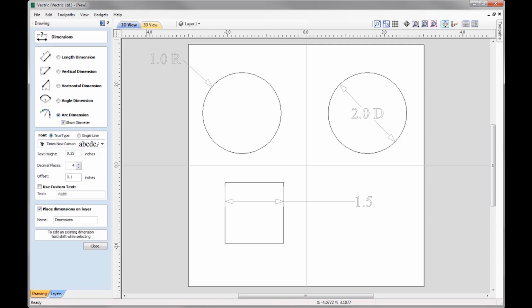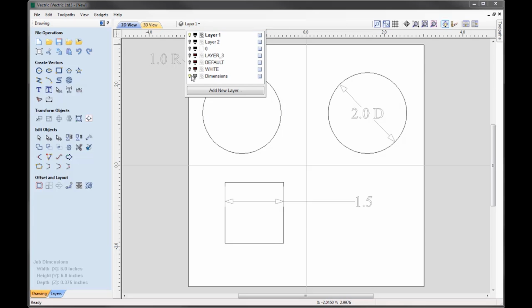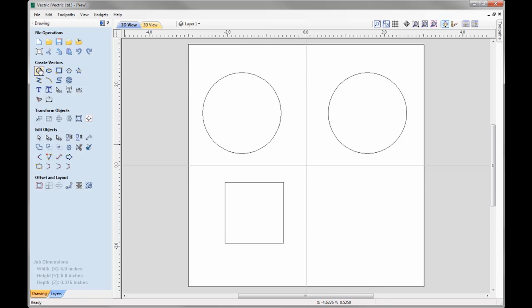Another enhancement we've made, which you saw briefly here, is the ability to edit shapes whilst in the relevant shapes form. So you saw that I held down Shift while selecting a dimension in order for us to edit that. Let's have a look at some of the other shapes that enable us to edit existing shapes. So we'll close that down. I'm going to go to the Layers tab to switch off the Dimensions layer, and then we're going to go into the circle form.